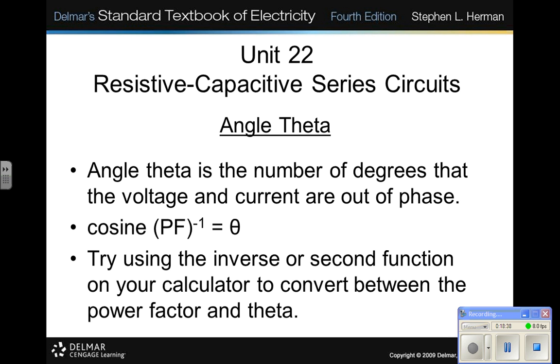The phase angle is the same between the resistance triangle, the voltage triangle, and the power triangle. Now, if we're talking about a parallel circuit, we don't have a voltage triangle anymore, do we? It's all flat. It's all the same, right? Parallel, voltage is all the same. Can't have a triangle. What kind of triangle, what factor will we have a triangle for in parallel that we don't have in series? That would be current. Okay, so we're not going to deal with that a whole lot here in this chapter. We're going to work with series, and we're going to work with voltage triangles, okay?